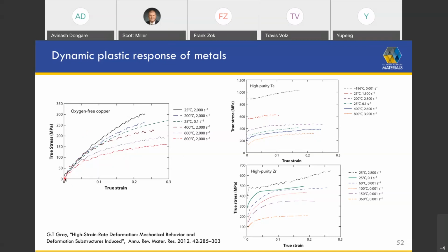It's on the order of a couple of MPa. Okay? And what you find is that strength doesn't depend on strain rate. The material, however, exhibits a very high strain hardening rate, as manifested in this green dashed line. Now, when you go to higher rates, you find that the degree of strain sensitivity or the strain hardening does depend to some extent on the strain rate.